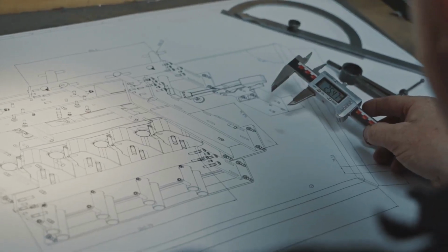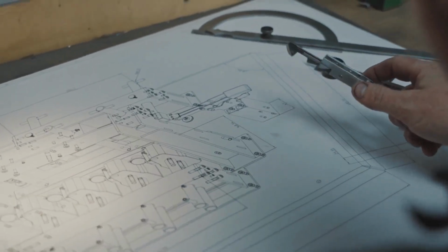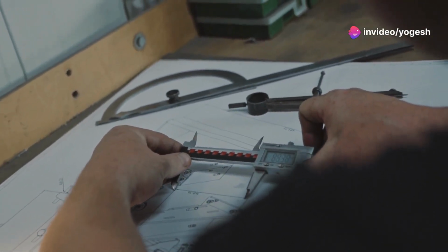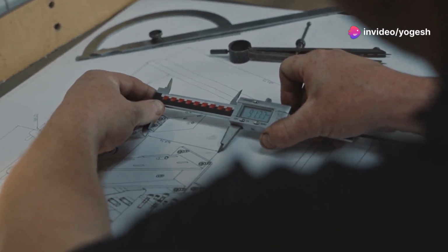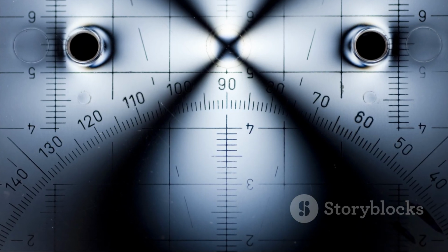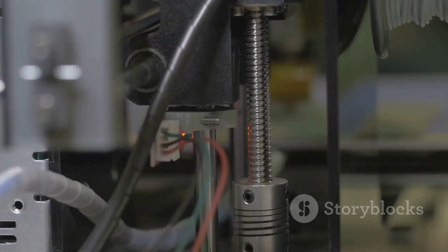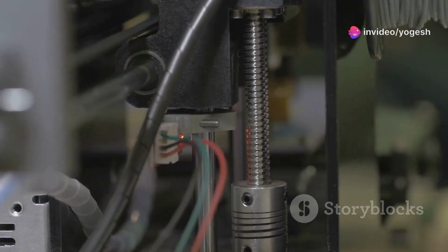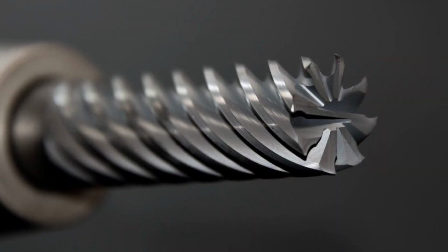For metric threads, the letter M, followed by the major diameter and pitch, is used. This system is standardized and widely recognized, making it easy for engineers and machinists around the world to understand and implement. For example, M10 by 1.5 represents a metric thread with a major diameter of 10 millimeters and a pitch of 1.5 millimeters. This notation is clear and concise, providing all the necessary information at a glance.